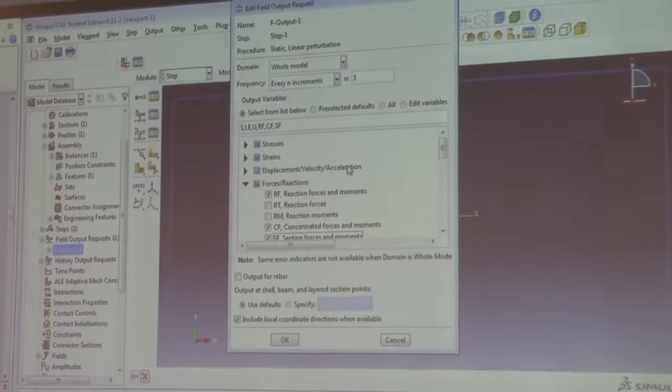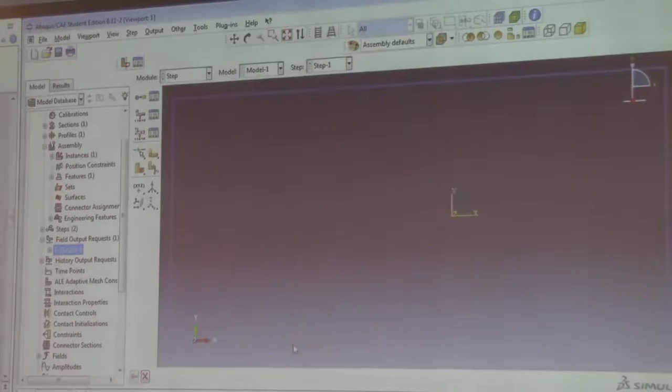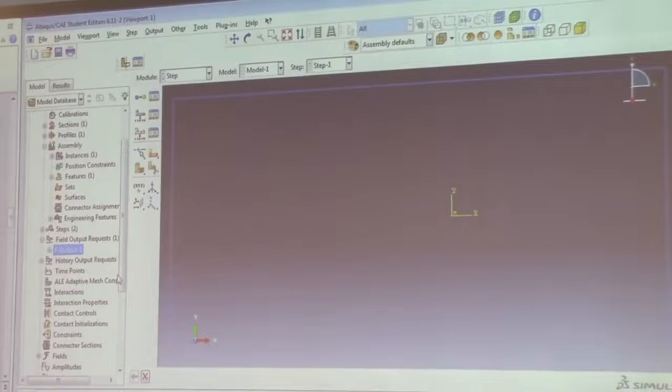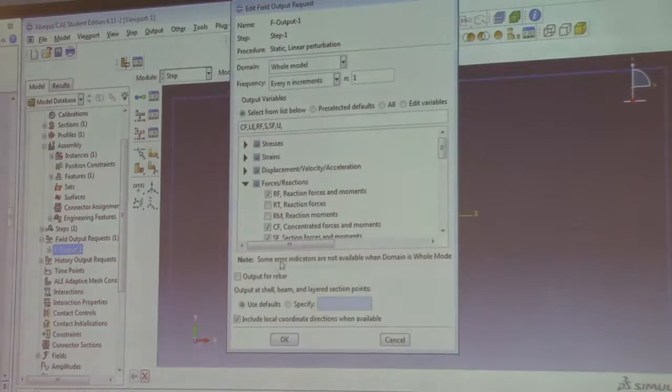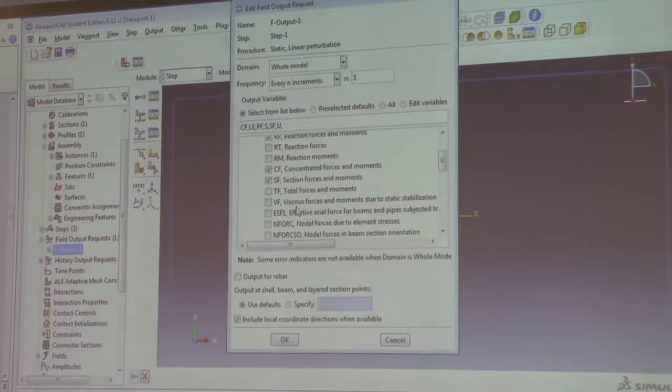And in the future, if you have a very complicated project, probably you have step 1, I add the horizontal force, and step 2, I add vertical force, and then create as many steps as you want. That is the purpose of steps. Okay. And it's just so that Abaqus can walk through it step by step. Yeah. So did I add it? Okay. Add it.